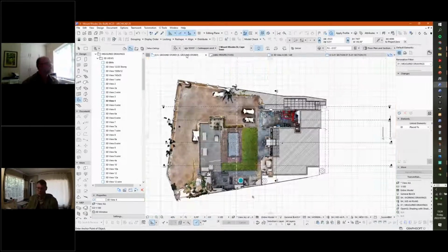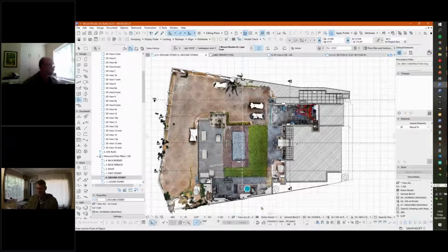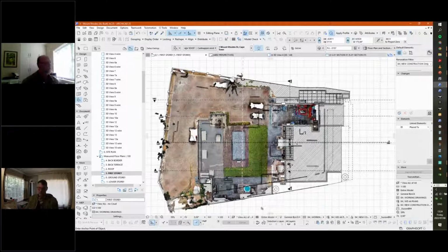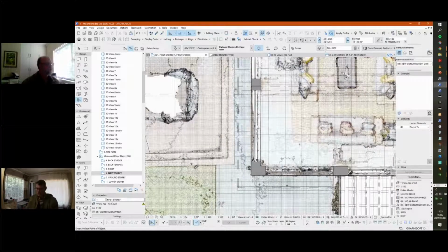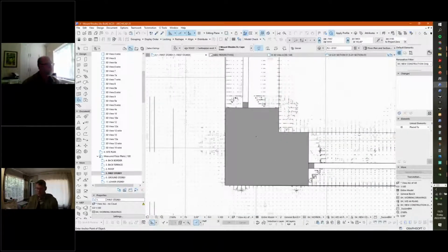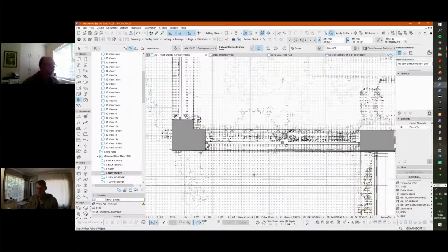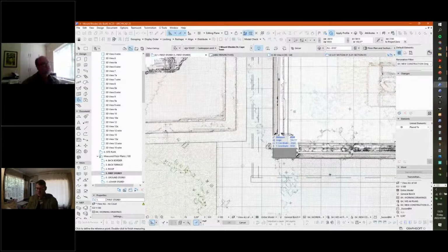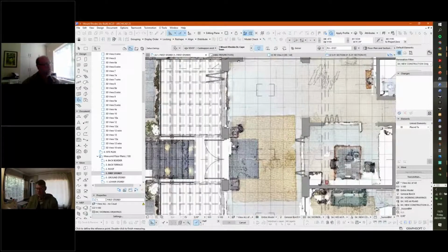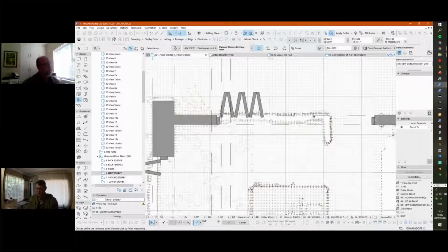If we go to the floor plan, and let's go to the top story here. You'll see this as being where the point clouds actually show up around the model. And just like we did on the section, you'll measure the point cloud where it shows you where the walls are. In this case, you'll see a stacking folding door. When it was scanned, this area here is where the stacking door was in the open position, only the opening leaf, and these other were closed.